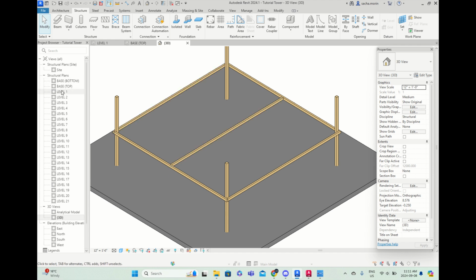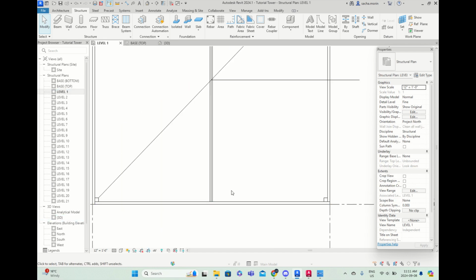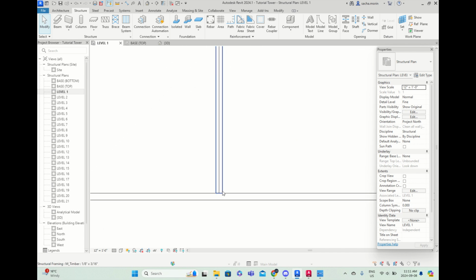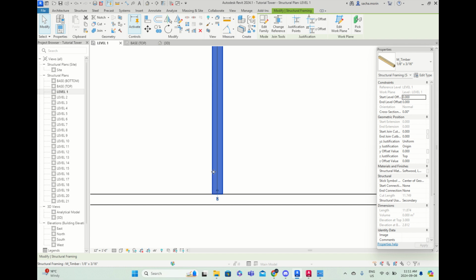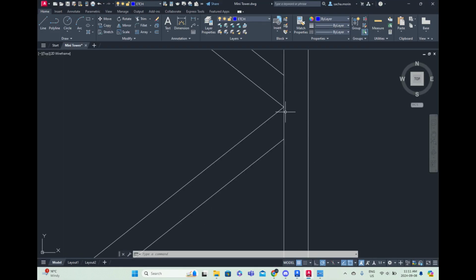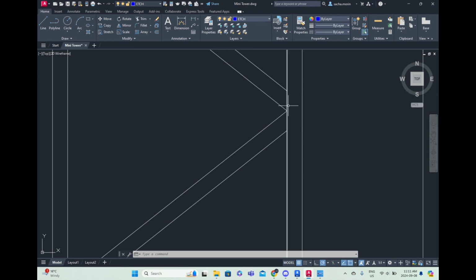Amazing. So now to make the diamond shape, there's something that you have to know about defining beams in Revit before we start. Every beam that I've drawn up to now has this squarish edge. All I have to do is draw a beam in Revit and the default will be this square edge. I don't have to worry about it. But if I'm making these non-square edges, these angled cuts, then I have to make what's called a reference plane that I'll be able to trim off the excess after and have these angled cuts.